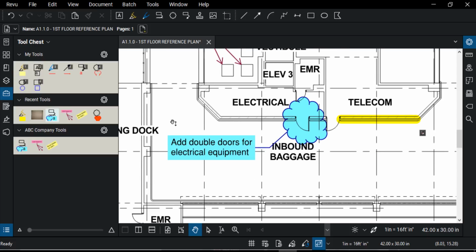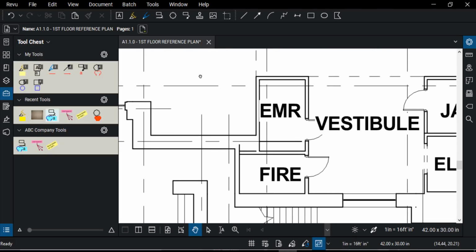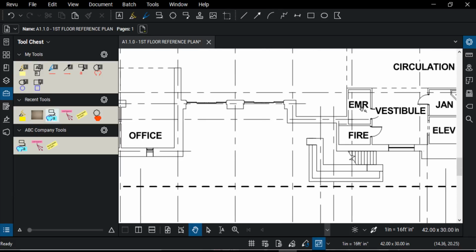Let's say, for example, I'm down here and I'm looking at this, there it is, this elevator maintenance room here. And I think, you know what, I want to change that elevator maintenance room to a storage closet. And so I think I want to use my Cloud Plus. Now, you'll notice that these symbols actually look a little different here. One of them looks like a Cloud Plus symbol, and you see the blue line and the light blue inside and the black text. Some of them actually look exactly the same as the first time I drew them.